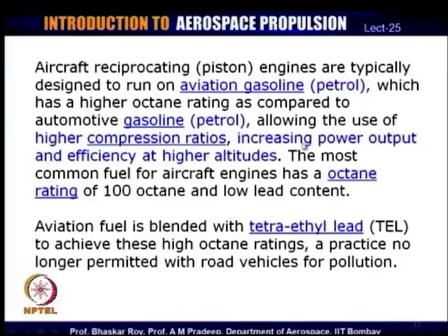Now, this kind of fuel is typified by what is known as high octane value. An octane rating is given in terms of 100, and the aircraft fuels are often of 100 octane, and they often have what is known as a small amount of lead content.